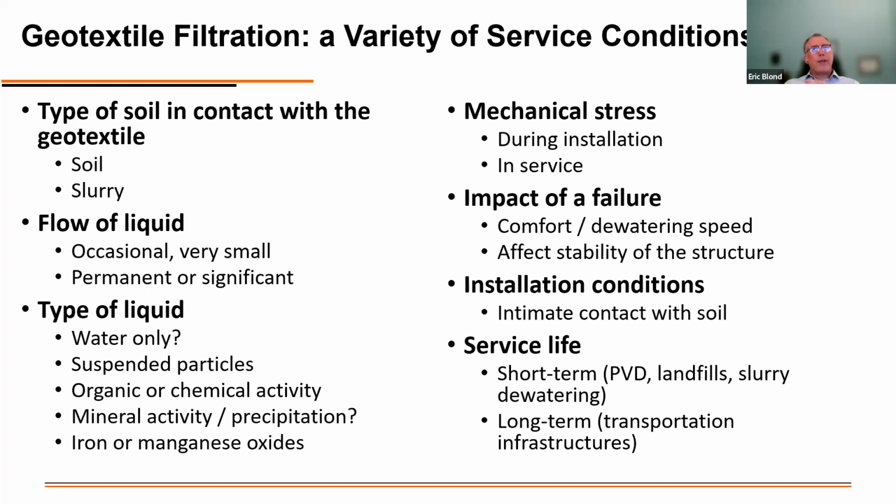That's actually a very important aspect, because accepting that the water is going to flow in 3 hours instead of 1 hour is sometimes very reasonable. While if we have pore pressure developing on the geotextile surface, and this pore pressure can affect the stability of the entire structure, like a veneer on a landfill, for example, on a landfill cap, this will have a tremendous impact on how we're going to approach the question.